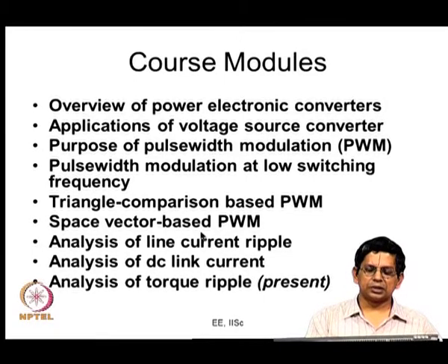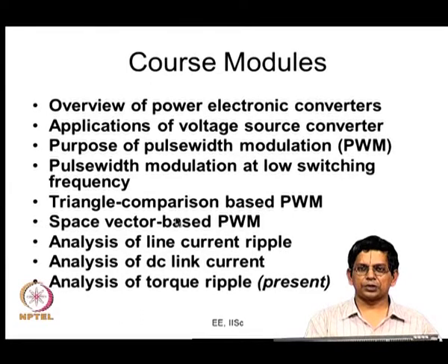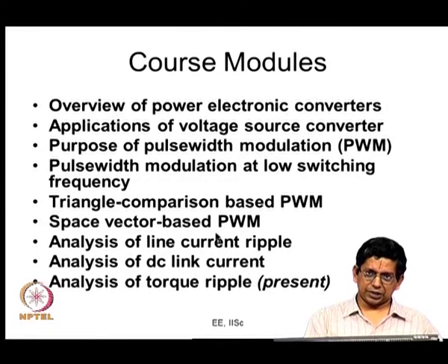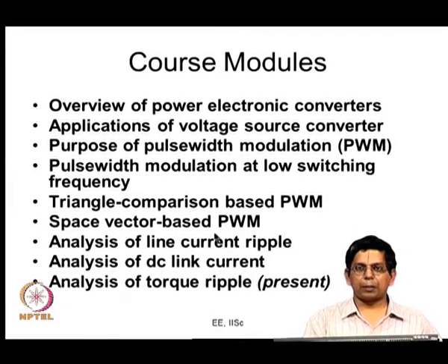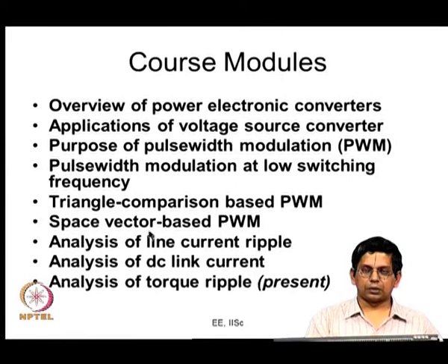All these methods, as I mentioned before, can be implemented either using a carrier comparison approach, that is, you can have 3-phase carrier waves and compare them with 3-phase modulating waves and produce the PWM waveforms, or you can use the space vector approach where the reference is provided as a 3-phase revolving voltage vector. This voltage vector is sampled, and you apply voltage vectors and use the time averaging of different voltage vectors produced by the inverter to synthesize it.